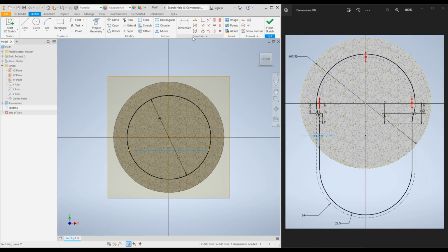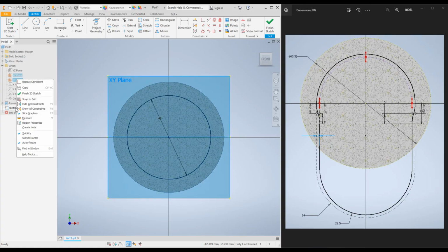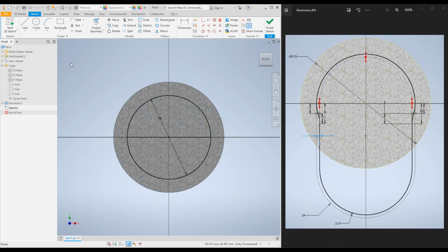What I'm going to do is use the constraint panel and use the coincident constraint, click on this line and click on the origin. Now the sketch is fully defined. You can see on your lower right hand corner the sketch is fully defined. Let's go ahead and hide those sketches as well. Hide those planes. Select with control all of them, then right click and untick visibility.